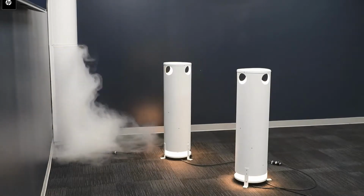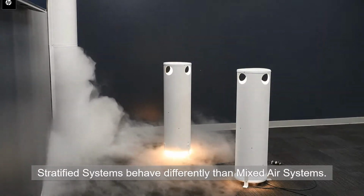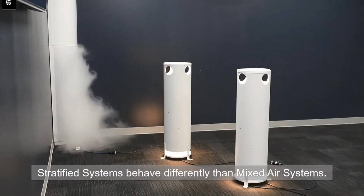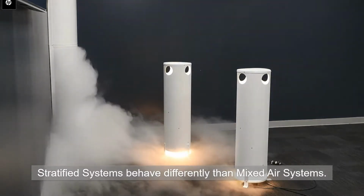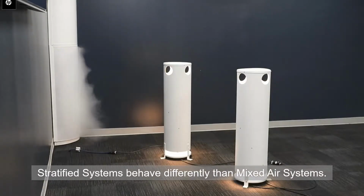An alternative room air distribution method is what we call a stratified system. In this case, this is a displacement diffuser. This is functioning differently than what we saw previously. This is a low velocity system. We're not forcing the air into the space, but instead it's supplying this cool air, almost like dumping it like a bucket of water. It's dumping this cool air onto the floor of the room.